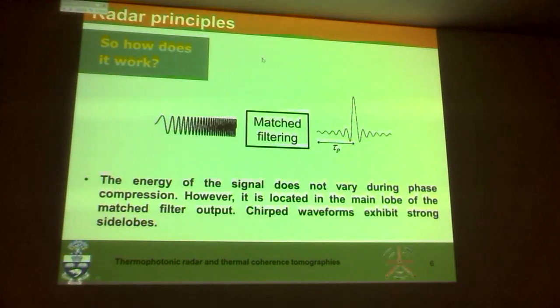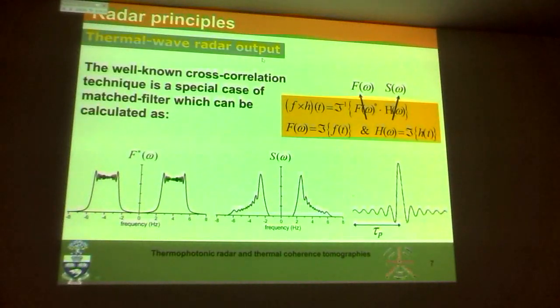This has been used a lot in non-destructive testing as well, because that's what you want to do. A lot of times this is very useful. If a material has a defect below the surface, that interrupts the flow of heat, and you can see the defect as a change in amplitude and phase. I'll show you a couple of these things.